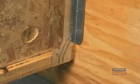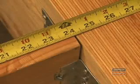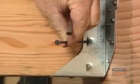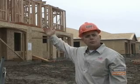Do make sure the joist is fully seated in the hanger. Do make sure that the joist is not cut too short. There should be less than 1/8 of an inch between the end of the joist and the face of the beam or header. Do make sure all recommended or specified fasteners are installed before loading the joist to beam connection. This means that you should fully install all the hangers on one story before starting construction on the story that will sit above it.